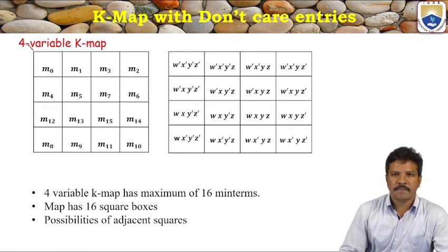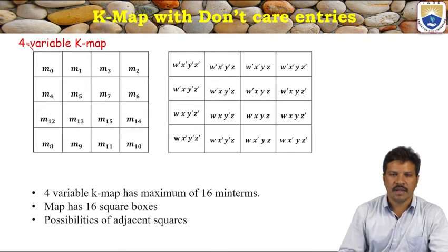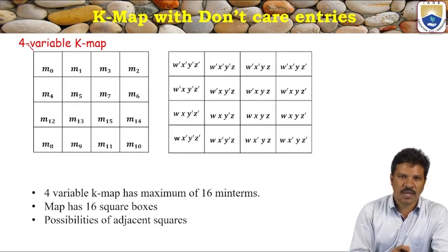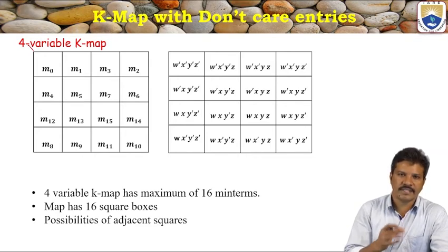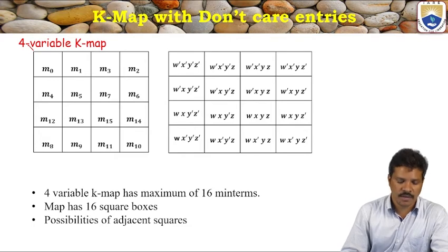If in a Boolean function all minterms are listed, we can take the logic symbol 1 to arrange all those minterms. So all ones are filled in these 16 square boxes. In this case, all are adjacent, so the entire set of variables is minimized into a single Boolean logic 1. The output is 1.